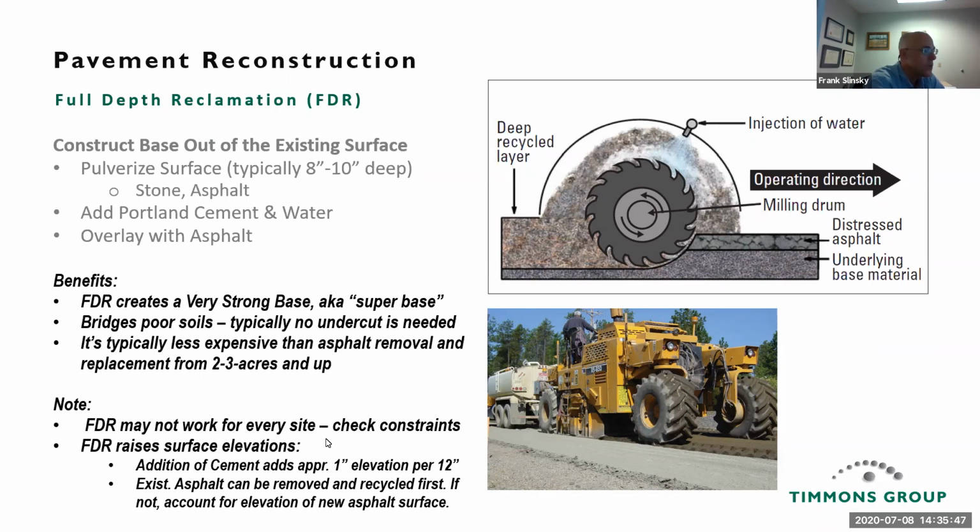It's worth noting that when the material is pulverized in place, it can be graded. So if you do have curb and gutters and you're concerned about raising elevations, this may be a good opportunity to change your slopes with a little bit of grading. You've got to be careful of not overgrading, but that can be done.